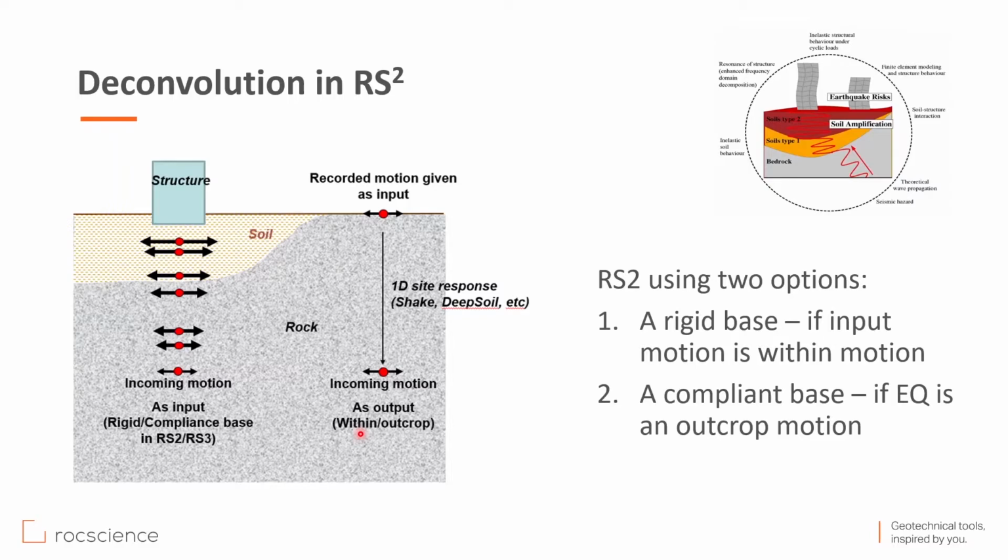The base still reflects the downwards wave propagation back to the model. A compliant base, where compliance will be activated when users select the compliance base option in the dynamic loading dialog. When the compliance base option is selected, the applied motion will be transformed to applied force in this case.